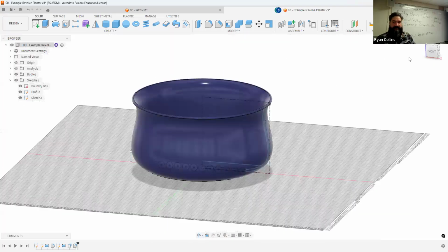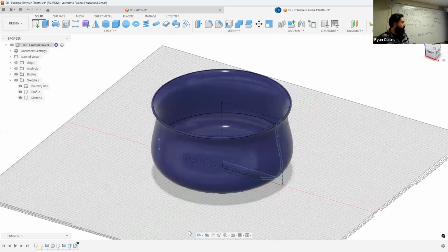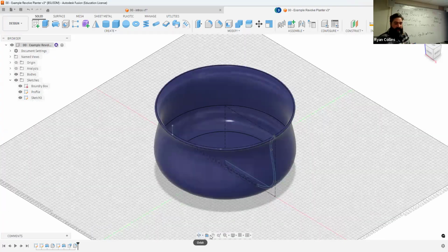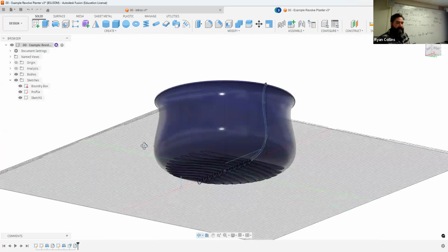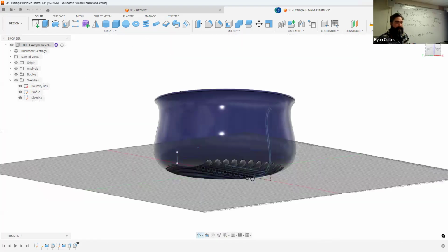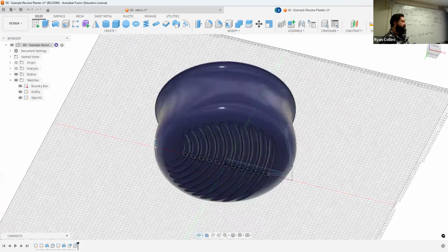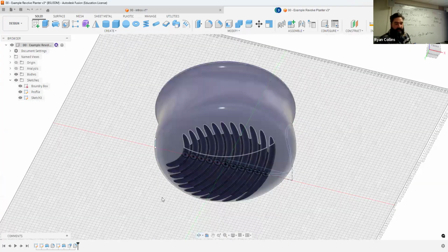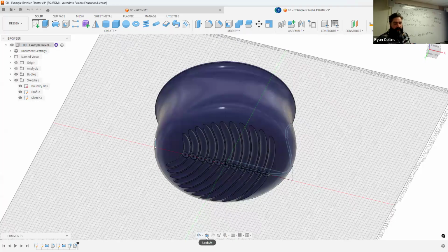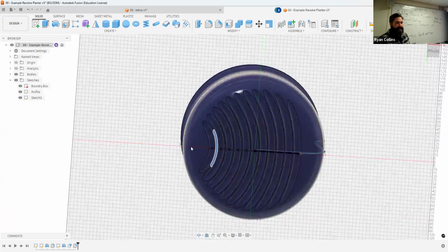If you don't have a mouse, you have the bottom options down here. The first one is orbit. Click that, and now you see your orbit. Your cursor has turned to an orbit symbol. Now I can click and orbit. Hit escape to get out of the tool. The next one is looking, and you can select something and it'll snap to.